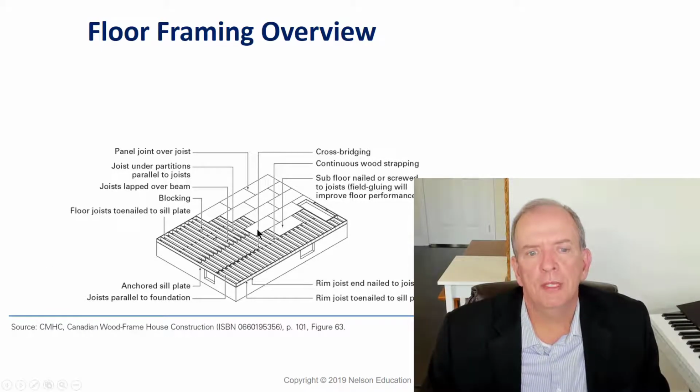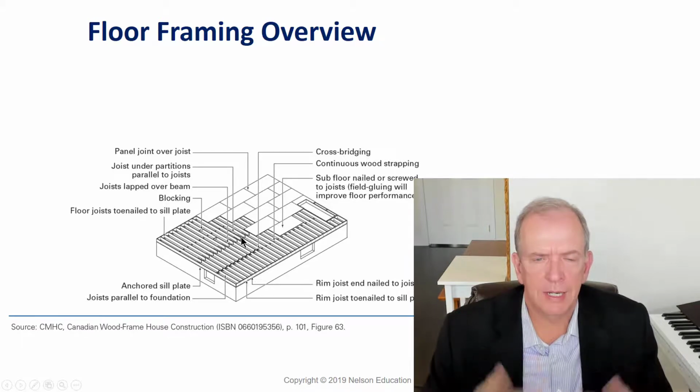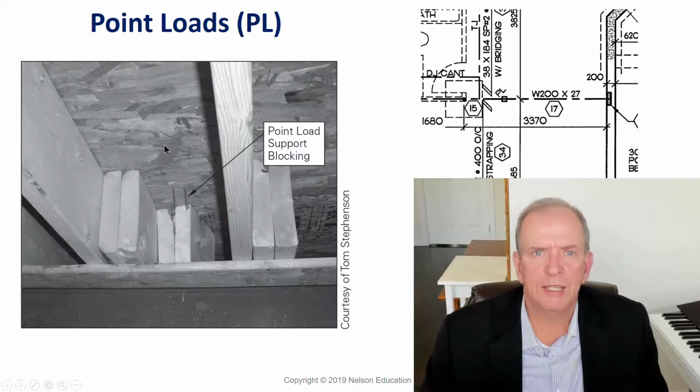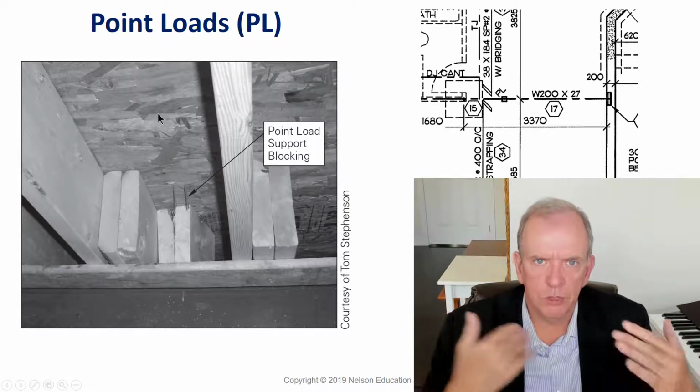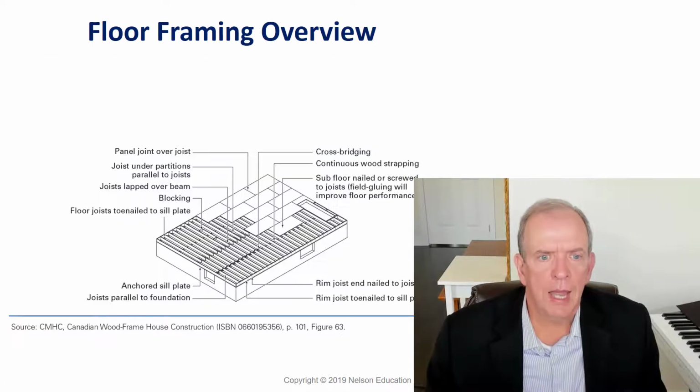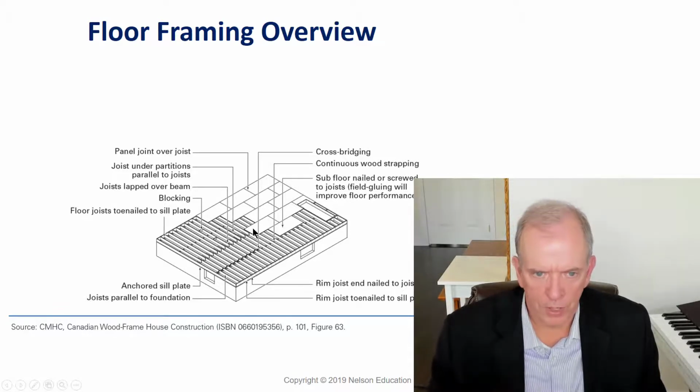And our subflooring material is always made of plywood or OSB. OSB, it kind of looks like, maybe there's an undershot here. See all that sort of flake board? That's what we call OSB or wafer board, oriented strand board. It's all these little chips of wood that are glued and oriented a certain way to provide the effective strength. And it's designed to go perpendicular to the joist. So the long way goes perpendicular across the joist.